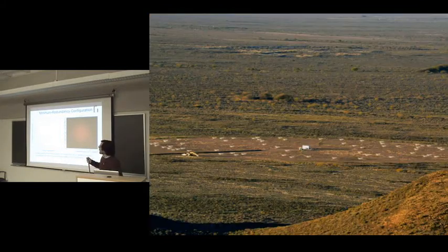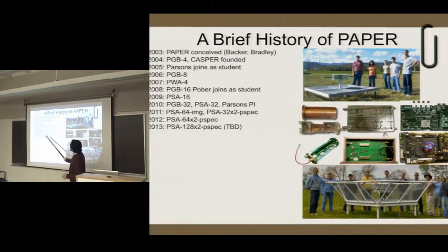What does times 2 mean? So when you have, say, 32 antennas, each of these is dual polarization. So you have a choice of correlating all the polarizations of each element, or you could hook up into your correlator just one polarization from each antenna element and get more samples of the UV plane, but you get no polarization information there. And so we've alternately been using these deployments where we use single polarization observations of 32 or 64, and then we can switch the same correlator to use 32 dual polarization observations. So we have these observations in hand. We've been operating for a month now, taking 64 antenna dual polarization observations. And then next year we will begin our 128 element dual polarization observations.